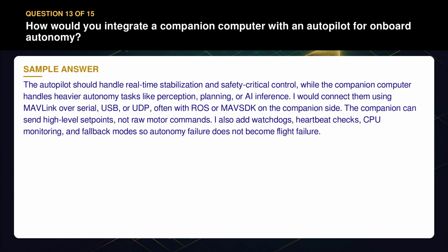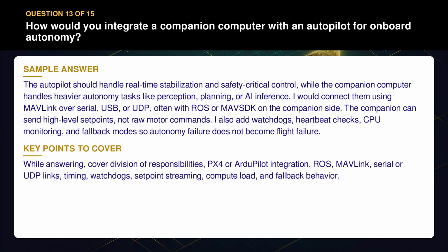I also add watchdogs, heartbeat checks, CPU monitoring, and fallback modes so autonomy failure does not become flight failure. While answering, cover division of responsibilities, PX4 or autopilot integration, ROS, MAVLink, serial or UDP links, timing, watchdogs, set point streaming, compute load, and fallback behavior.